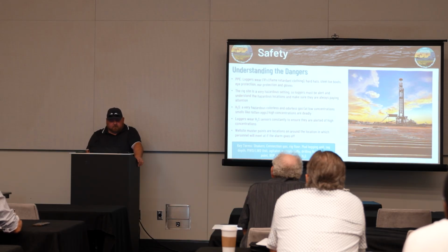Always wear your PPE. Standard PPE for everybody on location is FRs, hard hats, steel-toed boots, eye protection, safety glasses, hearing protection, and 99% of people on location wear gloves. It's hard to see a company man with gloves on usually.